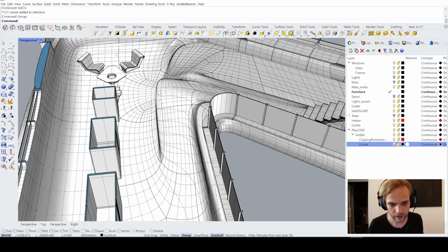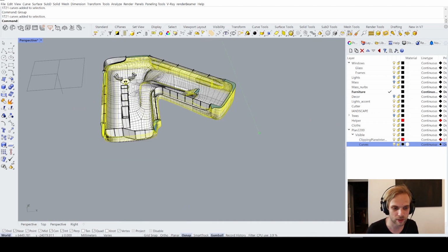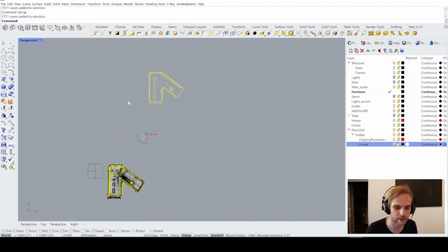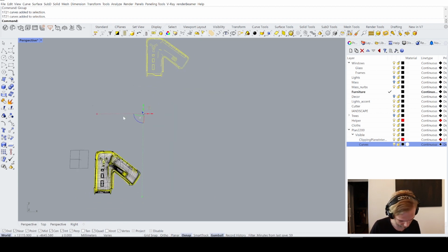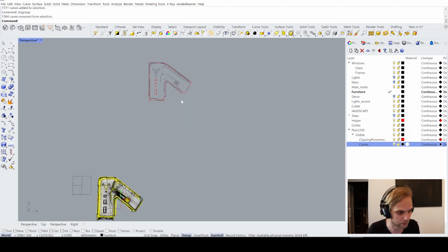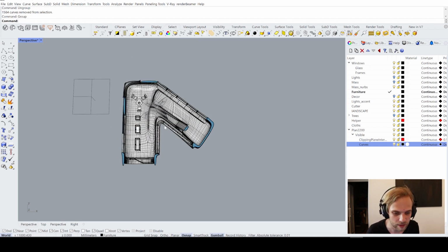And we will be using make2d on them, right? So that is going to be our second layer that is going to be added. Or sorry, I accidentally grouped the plan together with the contour lines, ungroup. So that is going to be our second layer of information that is added on top of our plan to